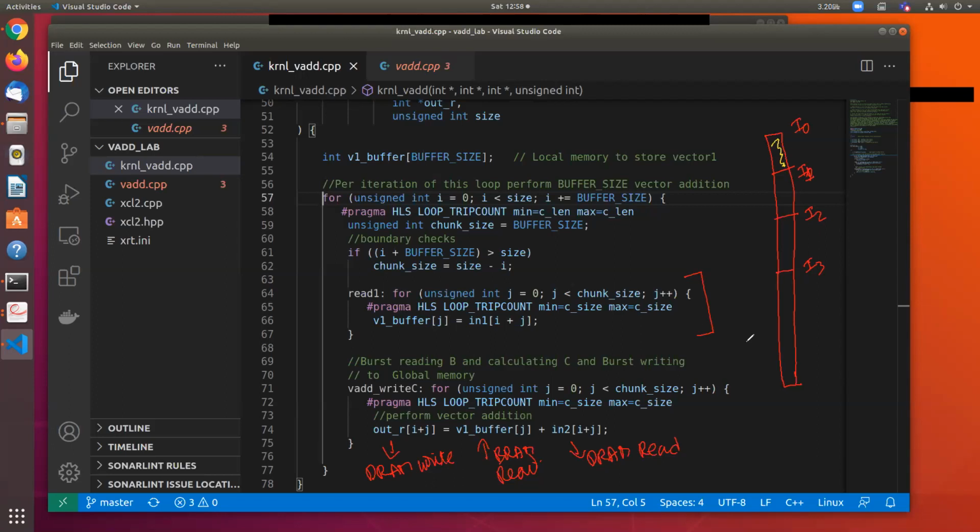If you look at this loop, the whole loop that is present in this function gets synthesized into hardware. Whereas in the case of GPU, whatever code is present here, there is already a fixed circuit on the GPU, and the instructions will be scheduled on them. But here, this circuit gets synthesized on the FPGA.